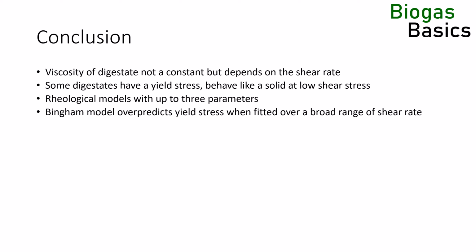Ideally, we use the Herschel-Bulkley model, but it has 3 model parameters, and a wide range of experimental data is required to fit the parameters. When choosing the rheological model, think first what ranges of shear rates are expected in the application that requires the model.